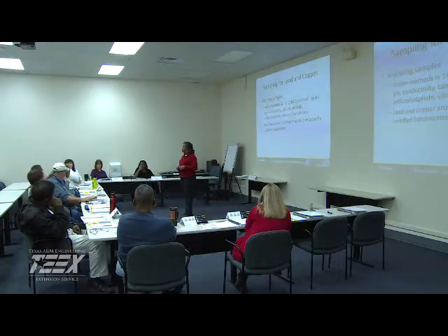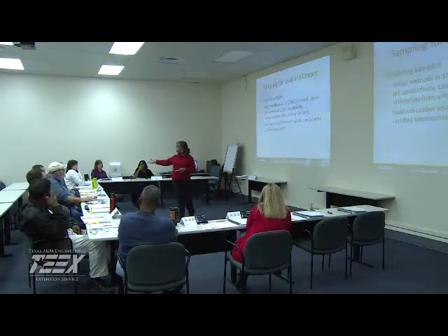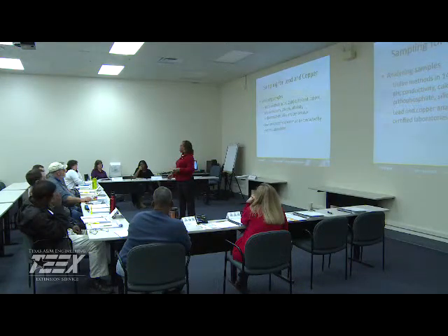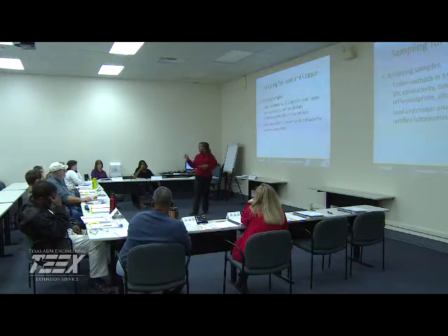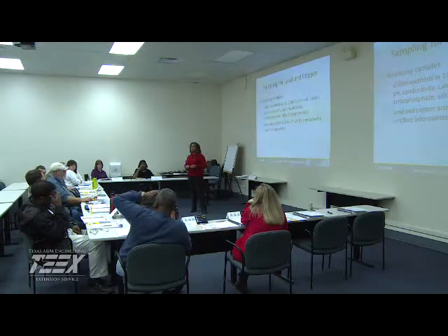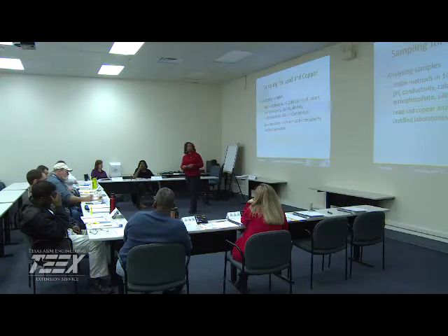For a pH test, if their person was on site collecting the sample and did a pH, we would accept that, but they're not certified for lead or copper. And for the pH, whatever group you're talking about, they probably have a meter that is EPA approved. That's a stipulation, because we accept it when our staff do the pH readings in the field when they collect samples, so we would accept it from a lab like EnviroCorp that's not currently certified for the other parameters.